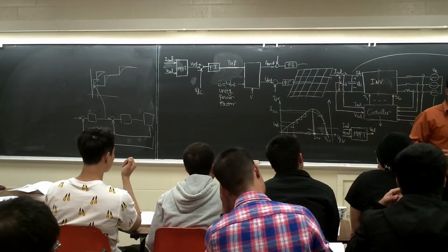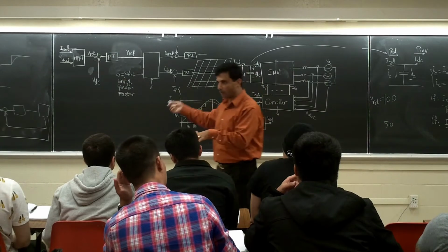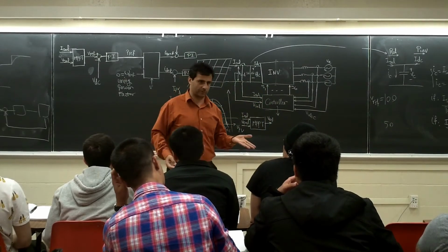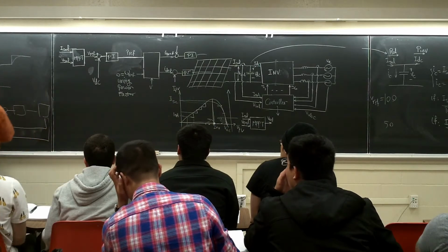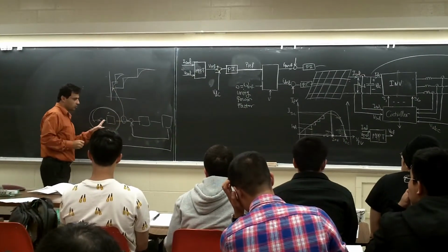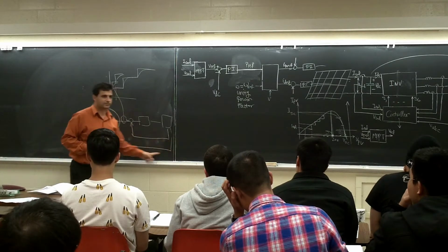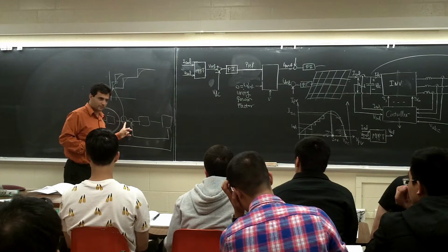This is the problem. If you change your reference faster than what you can catch up with, never ever are you going to get to that reference, right? So basically, how this reference is coming is the result of this one, right? So this one should be, by rule of thumb, 10 times slower than this.